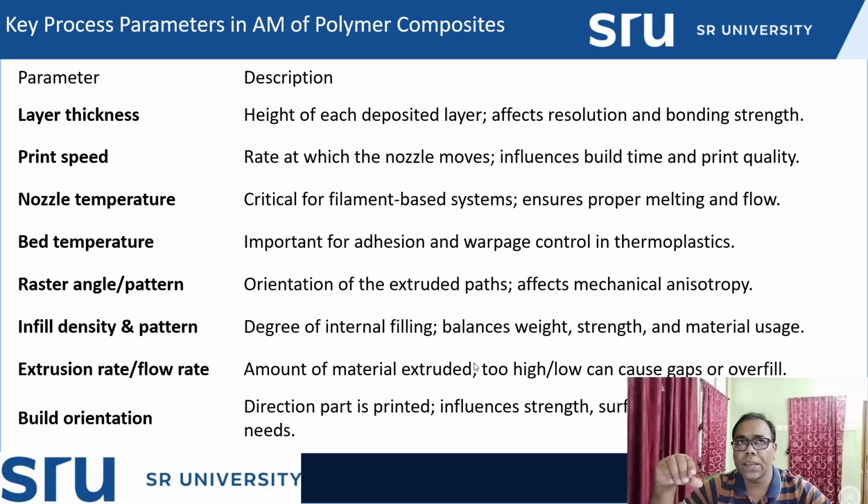Similarly, in a powder bed system, it is how your energy beam is supplied, or how your energy beam is scanning the area where the powder is already spread. That will decide the printing speed here. This will influence the build time and the printing quality. If your scanning speed is faster, what will happen? Sometimes the energy required to transmit from the laser to the material to be printed is not transferred properly.